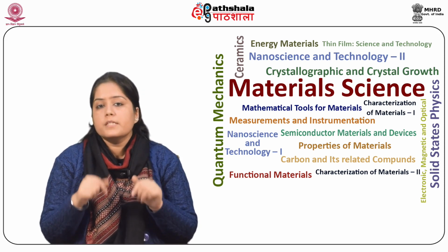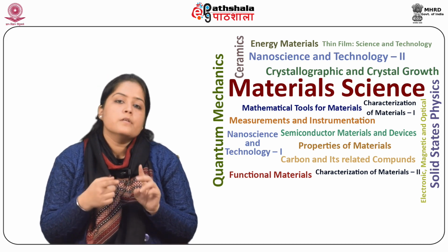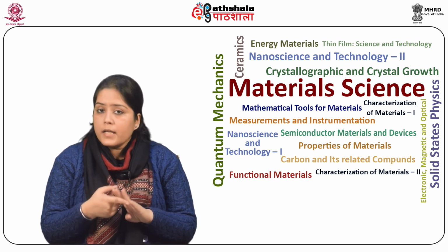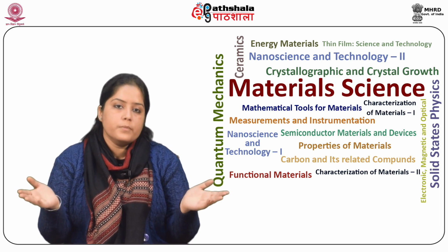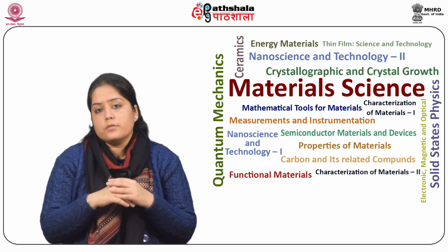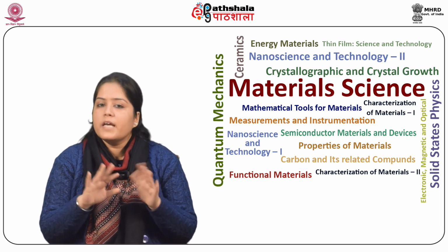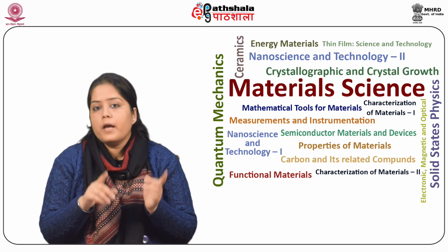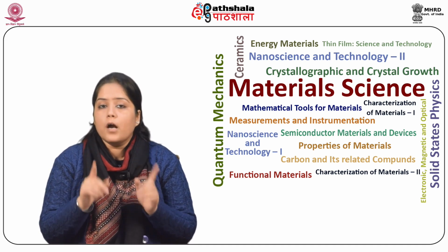The alloying materials such as titanium, zirconium, niobium, and molybdenum have broad solid solubility in uranium at elevated temperatures. Vanadium and chromium have reasonable solubility, and tantalum and tungsten have the least solubility in gamma uranium.